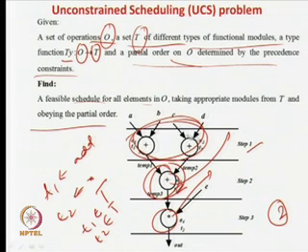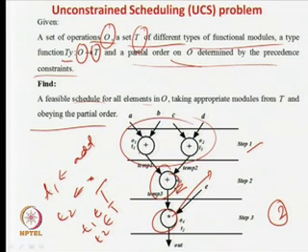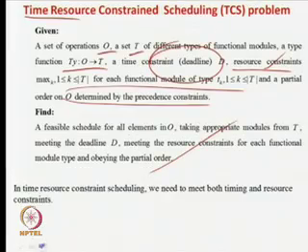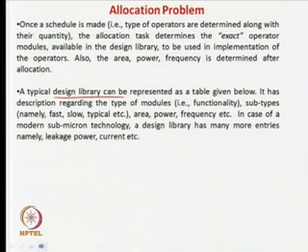Like in this case we may think about this example. These are two different adders working in parallel, so you have to put two adders. You can take this one as a ripple carry adder and this one as a carry look ahead adder. This is also possible, they are both adders, but they can be allocated different actual hardware elements. So, allocation takes the schedules you already made, and you take the exact hardware that is required and put it in.